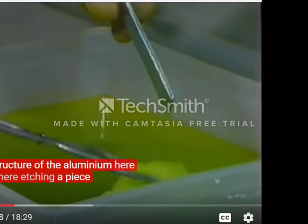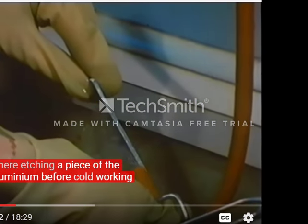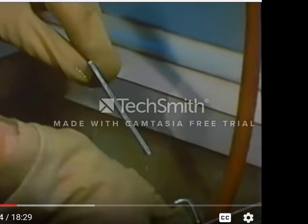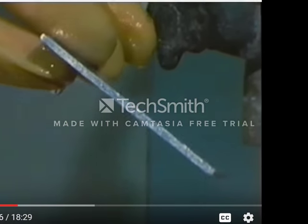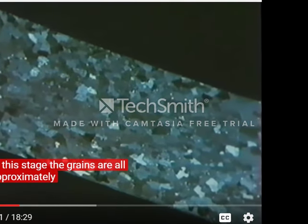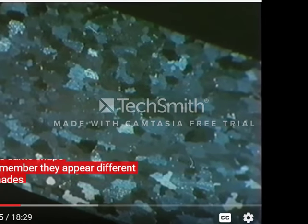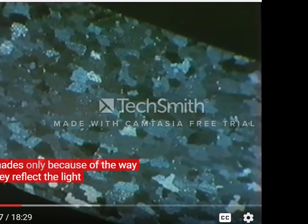Here we're etching a piece of the aluminium before cold working. At this stage, the grains are all approximately the same size and the same shape. Remember, they appear different shades only because of the way they reflect the light.